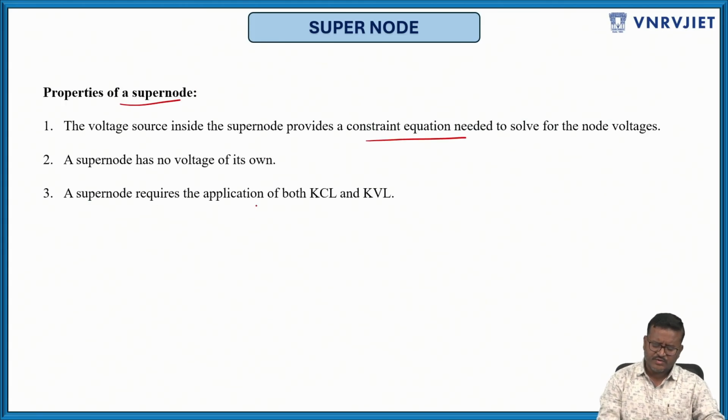And the super node requires the application of both KCL as well as KVL. To do nodal analysis, the essential thing is the application of KCL. But whenever you have a super node problem, you have to apply KVL also. These are the properties of the super node. Let us see one more problem.